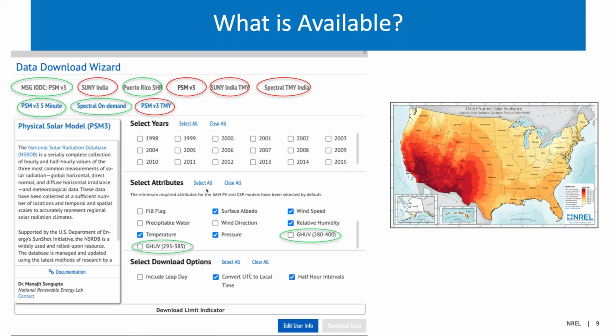So if it's January, it's a median of all the Januaries within our data set, Februaries and whatnot, and that shows up in the TMY, but it's only for a horizontal orientation. So what we found is that that's okay if you put your PV panels in horizontal. We never do.